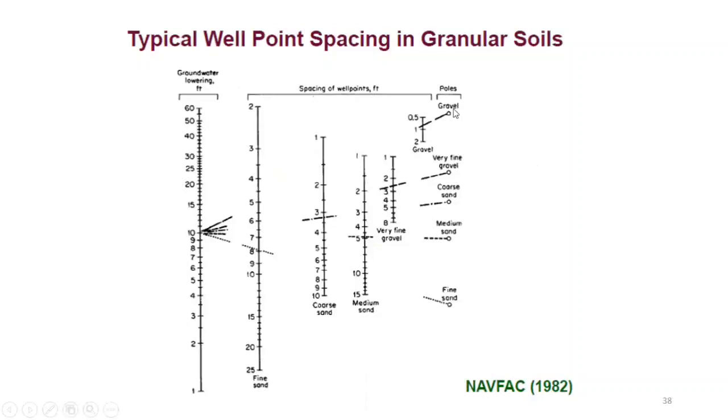So your reference soil is gravel. You will draw a line from 10 and move to the gravel. And then you can see the spacing would be, for example, in gravel over here, about 1 foot. So you have to install very closely spaced pumps.